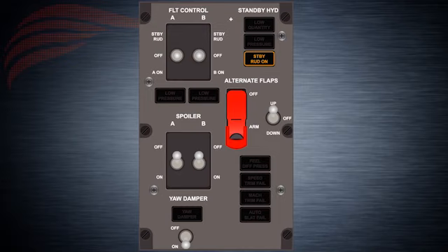When the switch is in the standby rudder position, the standby rudder shutoff valve controls the low pressure light through the valve position relay. The low pressure light comes on when system pressure is less than 1300 psi. When the low pressure light comes on, there is a master caution and also the flight control annunciator comes up.